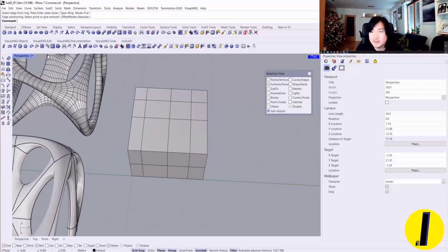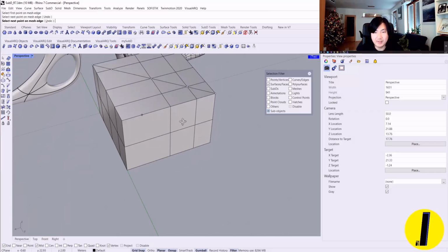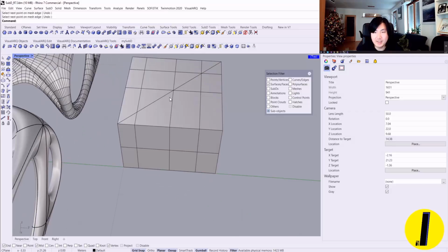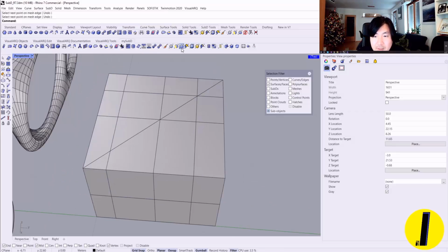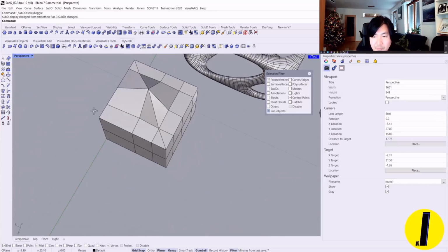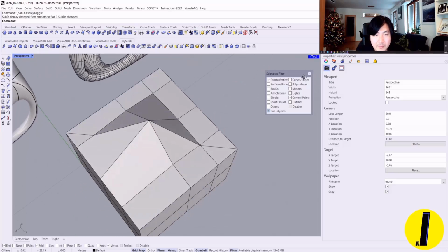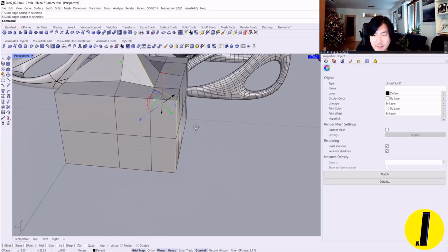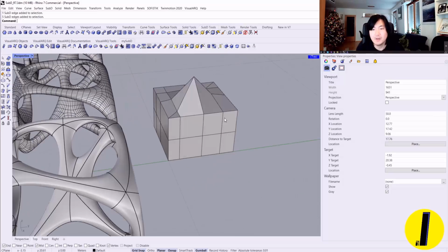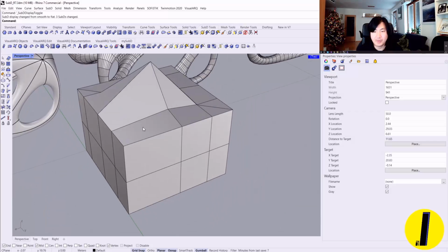There's also a nice tool. We can also insert a point to the mesh or subdivision. So when I click, I can select subdivision, and for example, if I cross from here to there, then the entire edge is added. So let's say I click vertices, click that, and if I move it, as you can see, we can change the geometry because we inserted a new edge. If I disable that and select this, we can also extrude it if you want. So there's a lot of possibility with this insert edge command.